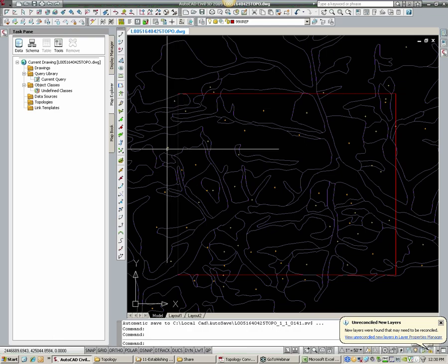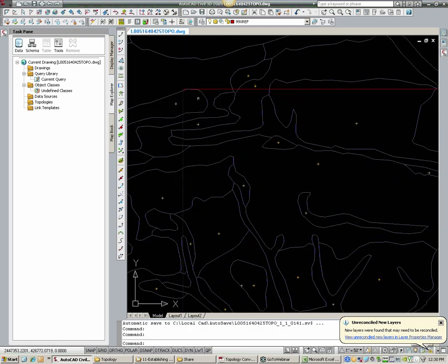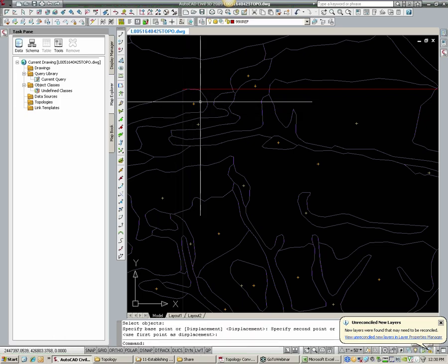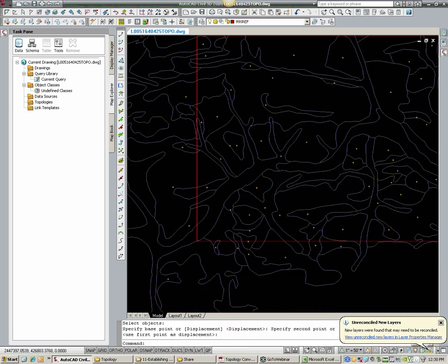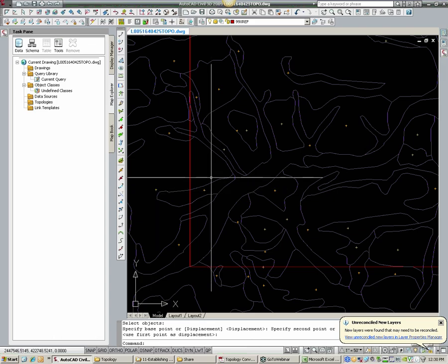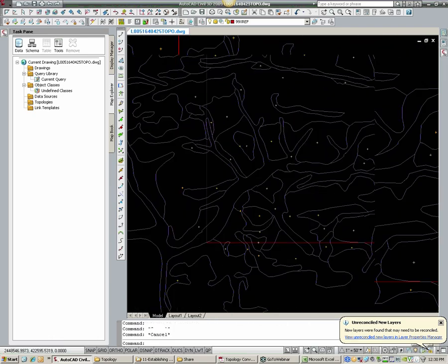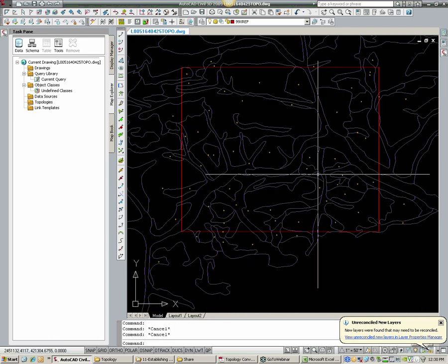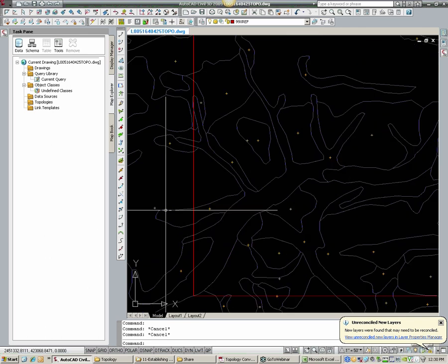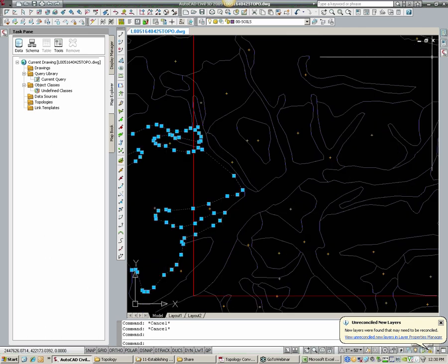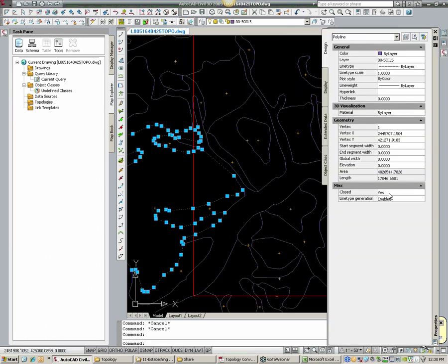These little dots I need to move in to be inside of my rectangular area. But it's not that straightforward, because some of these dots, like this one, actually have to be here and here, because you can see that boundary comes in. There's areas inside on either side. It's actually up here as well. So you have to go around the entire perimeter and do that. And really what you get messed up with is when I click this polyline now, since I ran that create centroids command, it doesn't have any more object data assigned to it. So how do I do this efficiently?